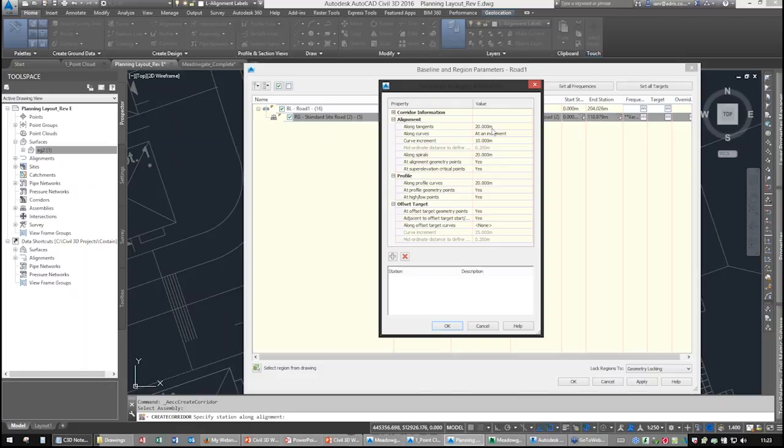On a slightly bigger road, maybe a 30-mile-an-hour road, then you might want to do it even every 10 meters. And in fact, most of the large companies that you work with don't really want points beyond every 10 meters, it gets too big. But I would usually drop that to about 10, and then along the curves you drop it to maybe about 5.